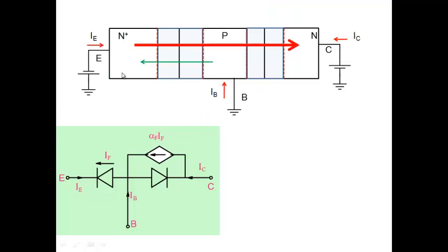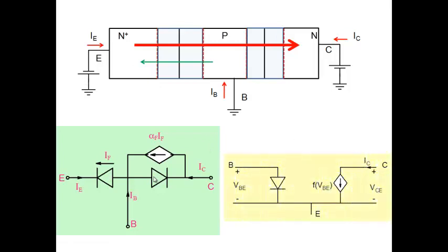Okay, so my bipolar transistor under this configuration can be represented by a diagram like this. Another way that I can represent it is in this form. So here we are using base as a sort of common terminal. We are writing emitter here and collector here. Now we have used emitter as a common terminal. So we are saying between base and emitter, there is a diode, which is fine. And note that this particular diode doesn't conduct because it's reverse biased, so I can remove it also.